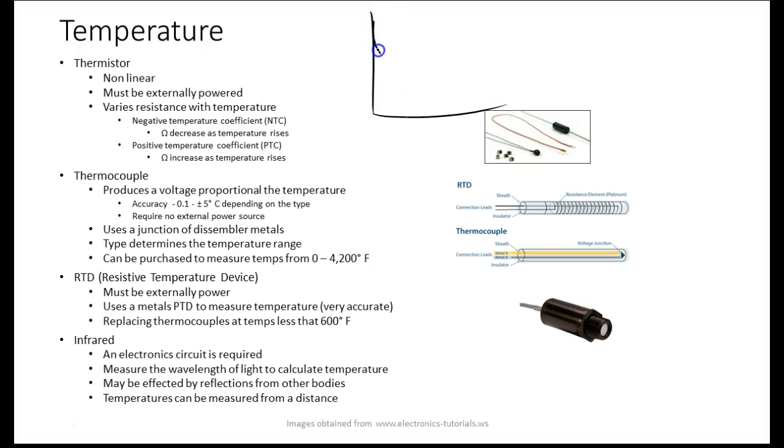So the curve kind of looks like this, so it angles like this, if I can get that right. So if temperature goes up, and this would be for an NTC, and then this right here is R. So as temperature goes up, then R would do what? It will go down. It's at a slope. Normally what they do with a thermistor is they'll give you different ohms at different degrees. Now if you knew that, then you can compensate for the slope, especially with a computer.